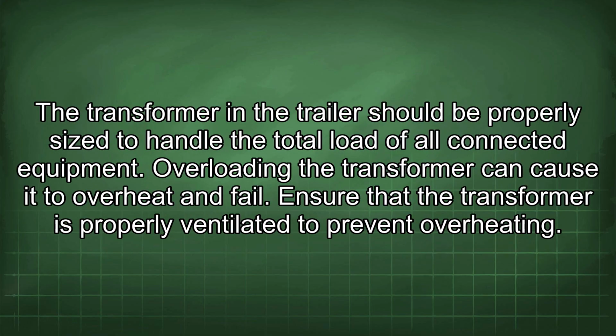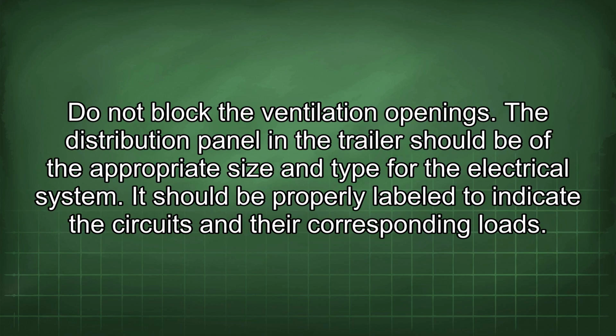The transformer in the trailer should be properly sized to handle the total load of all connected equipment. Overloading the transformer can cause it to overheat and fail. Ensure that the transformer is properly ventilated to prevent overheating. Do not block the ventilation openings.